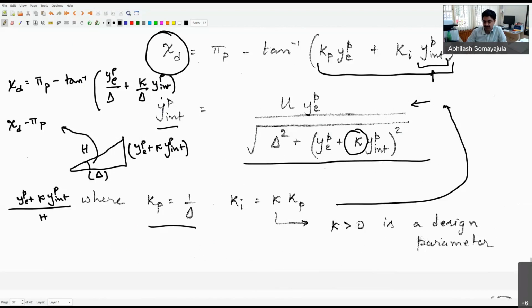Yes, I have introduced a more complex nonlinear system rather than a straightforward case where I was simply adding an integral term, but I have gained something in the sense that I have a guarantee that the system is globally asymptotically stable, which means that no matter what happens, the cross-track error will eventually come down to 0, and it will eventually always try to drive my system to make sure that my cross-track error gets down to 0.